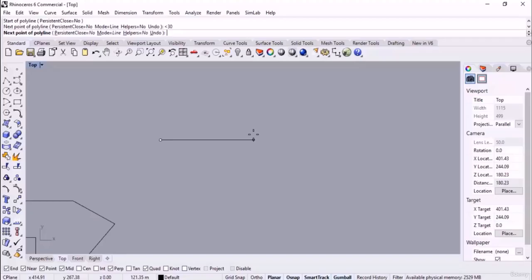So at first we specify the degree or angle. Then at the second stage, we should specify the length of the line. For example 4D, enter, and you could probably guess the next stage. Great. Here we should specify the direction or one of the 30 degrees parts or angles. Like this. I click and then we can have our angled line.